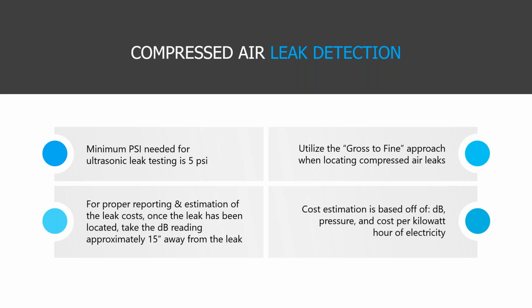I can stand back several feet away and turn up the sensitivity. In most cases, we want to increase that all the way to the maximum sensitivity. Then I simply scan that area left to right. I'm holding the ultra probe in my hand and I'm scanning left to right, and up and down. We really use our ears as much as our vision, so the sound will actually lead us in the direction of where it's coming from.